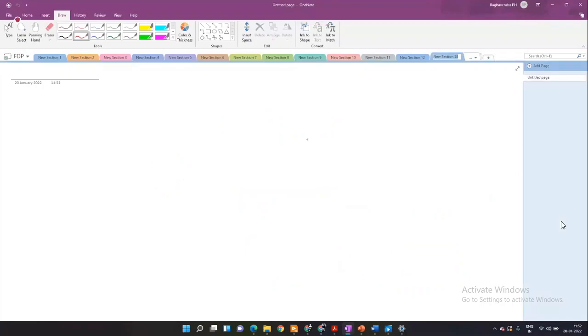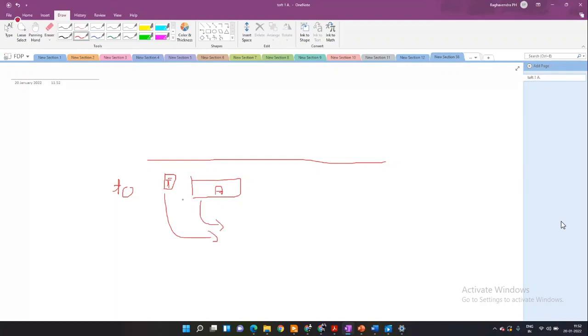Let's say I've actually seen people do this project. There's apparently a road where you have a temperature sensor and an accelerometer, and they try to do some machine learning process on this. Now it is crucial, especially with sensitive things like machine learning, that if I want to take data at T naught, temperature and accelerometer, and then do some machine learning processes on this, both the temperature and accelerometer values are taken at the same point in time.